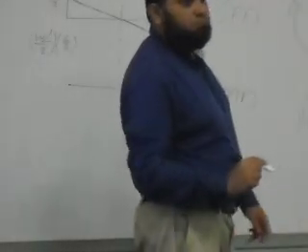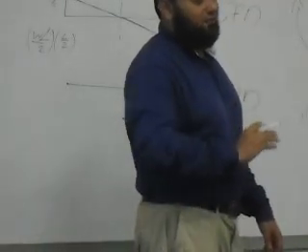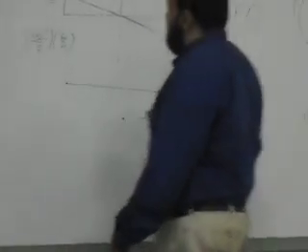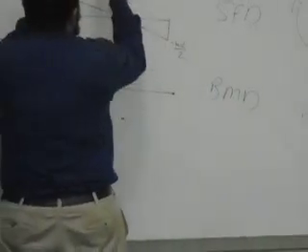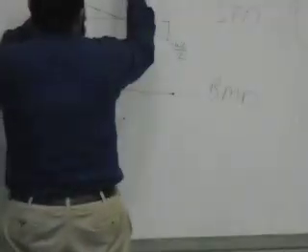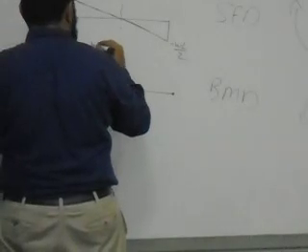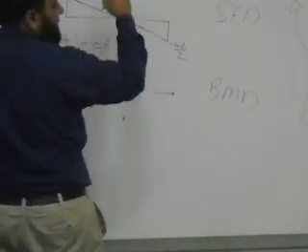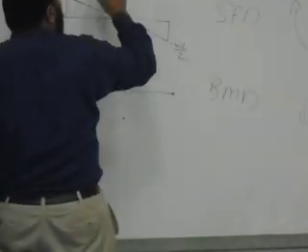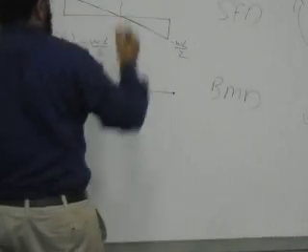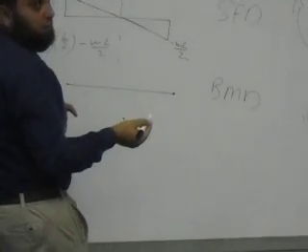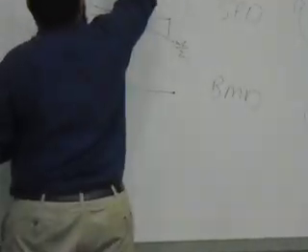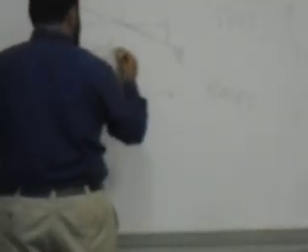I think that's the fastest thing ever you can remember. Smiley. Okay? But this is the sad guy. The sad guy is the load. This rectangle is what? W times L over 2. And where's the centroid of this rectangle? At the middle of L over 2, which is L over 2 divided by 2, L over 4. So that is WL over 2 times L over 4.